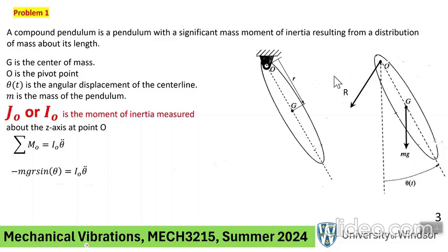From trigonometry, if you look at the distance from O to the extension of this line of the force, the moment arm is right there, and it's going to be r, the hypotenuse, times the sine of that angle. You just clean it up, and if you assume a small oscillation, so sine of theta is approximately theta, then you get the mother of all equations for this problem.